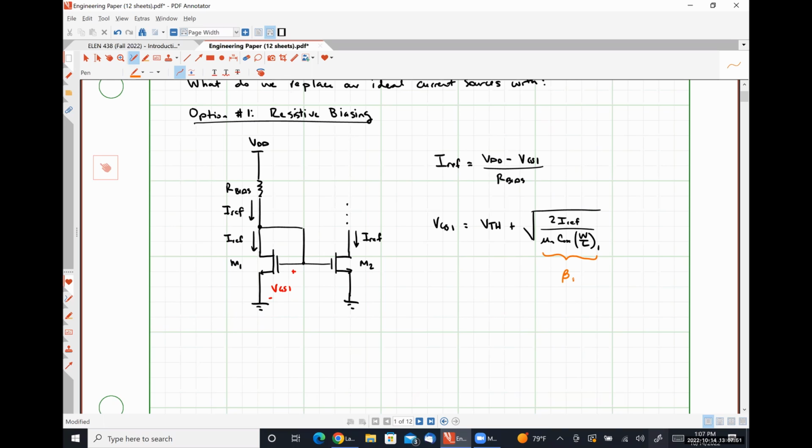It's the common emitter current gain, which for us would be a common source current gain. And we have a common source here because our source is tied directly to ground. Okay. So this is the MOSFET equivalent of the BJT beta effectively, and conveniently enough, it allows us to not have to write that whole thing down over and over and over again.